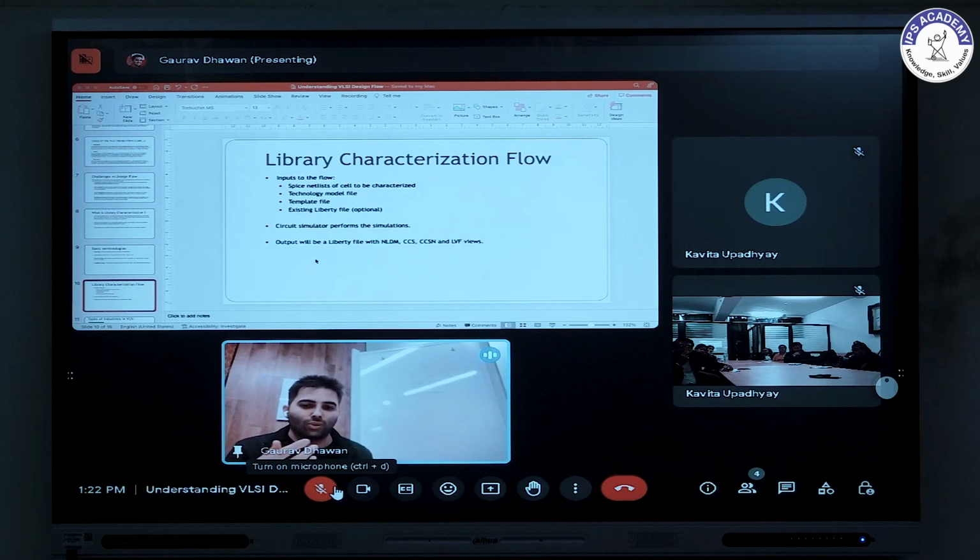So if I show you again the library, you can check that under the input pins. For example, pin D, right? Pin clock. So under these two pins, clock and D pin, if you see any power tables, internal power tables, those are hidden power tables. That my change in input did not cause any change at the output.